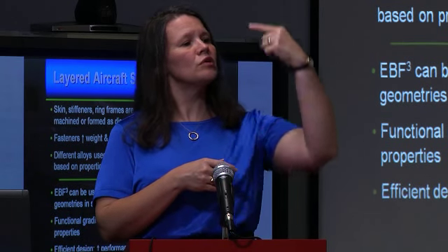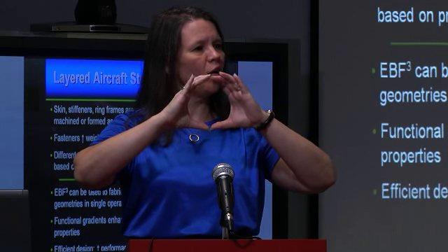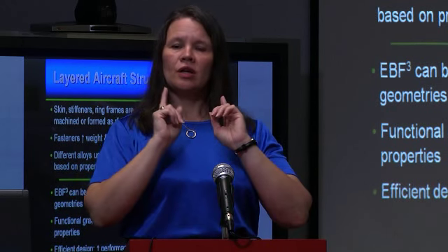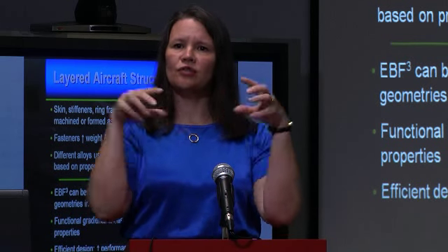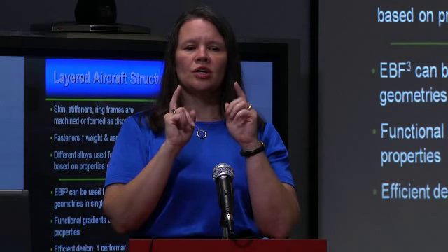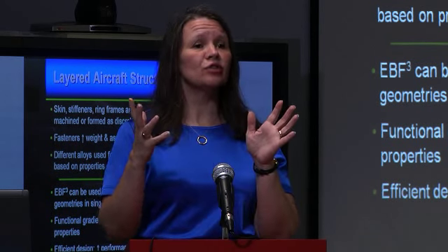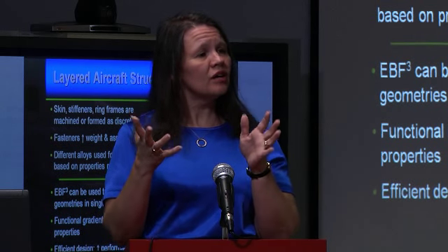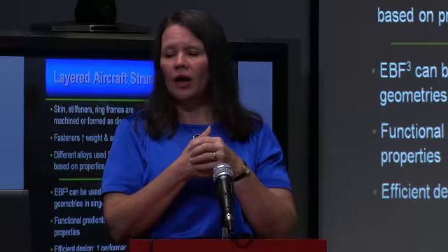So the ring frame goes in the circumferential direction around the fuselage to help with the hoop stresses. The stringers go parallel to the length of the fuselage. The fuselage is the place where everybody sits, along the length of the fuselage to give it stiffness. And the whole thing is riveted together. So it's thousands of parts. Aircraft industry is still very manual, and so these are all hand assembled.